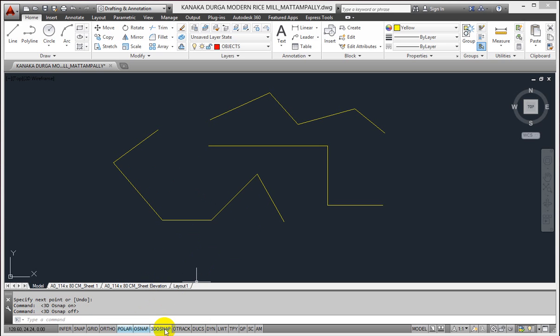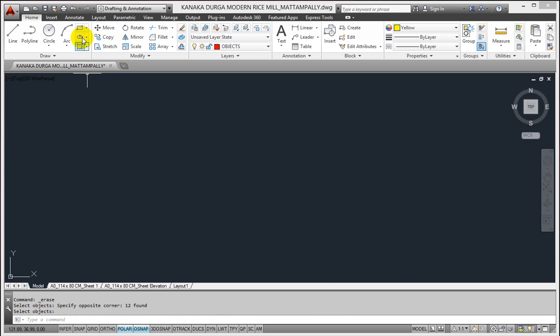The next drawing aid tool is O-Track. Use object snap tracking along with alignment paths. You have to use these alignment paths that are based on object snap points. Suppose I want to draw an imaginary line from this end point, or I will give you an easy example. Suppose there is a rectangle here.